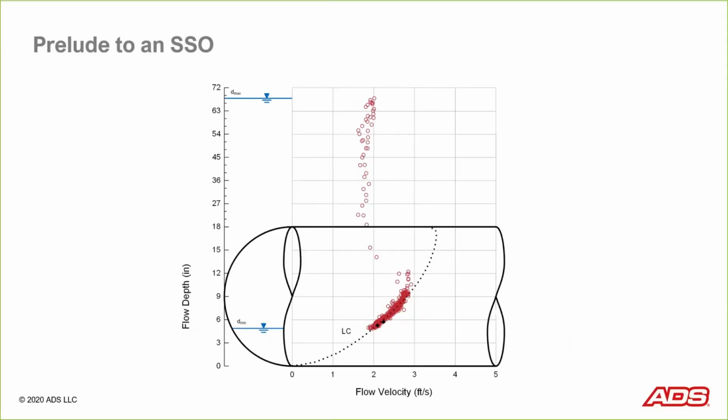And adding the Manning equation to this particular scatter graph allows us to see data that follows uniform flow conditions. And then you can see and infer what's happening in the rest of the data set where the data does not agree with the Manning equation. And in effect, that helps us define the three conditions that are going on in this data set.